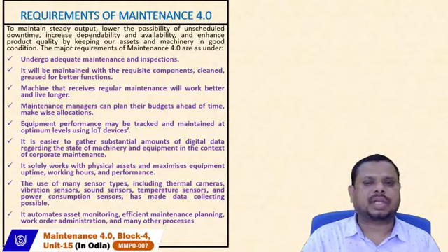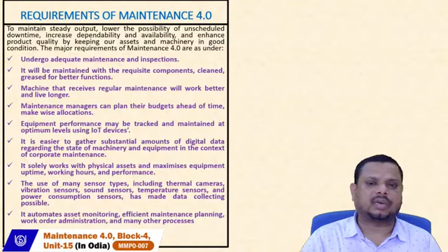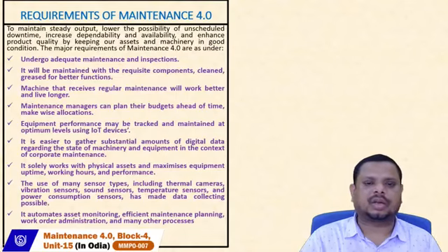Then sound sensors are basically used to identify and collect the varying sounds, whether the condition of the bearing is healthy or inefficient. Then temperature sensors are used in various high temperature areas, like in captive power plants, where the boiler components and the generator components are equipped with a large number of temperature sensors. When the temperature rises, the sensor directly indicates or communicates to the servers.